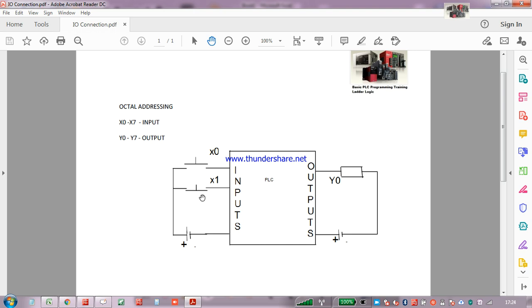How will it work? The NO element will be in open. NO means normally open, so the button will be in the normally open state. If we press this push button, the supply from one side of the button, that is the element, will get closed. So the supply from one side will pass into the other side, and through that wire it will get into the X0 input. It is a NO push button.